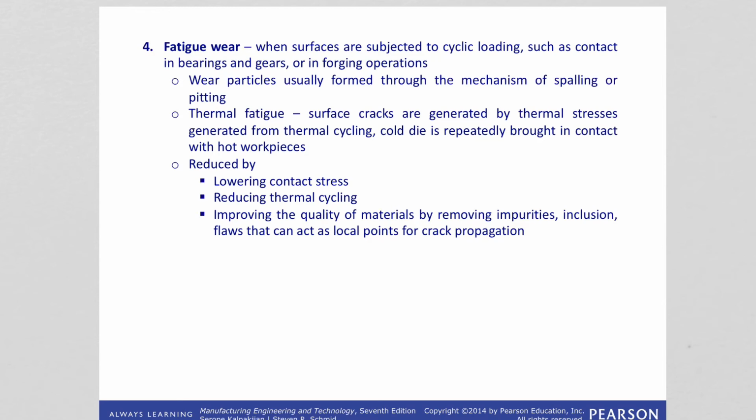And this is the same as at the surface. That is what is happening. There is cycling loading the material is exposed to, and this will form wear particles on the surfaces. Wear particles form through the mechanism of spalling and pitting.